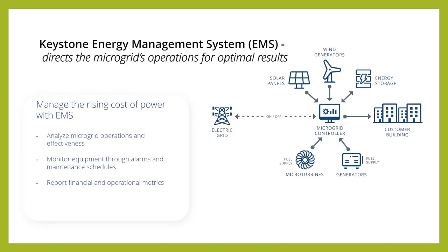People often ask, if you don't have these meter records, what can we do? And the answer is there's lots that we can do. We can use partial records. We can take records that are taken more infrequently. We can even go from past bills and build a model ourselves of what the building is probably doing in order to get this kind of data. So again, let's not let the perfect be the enemy of the good here. We'll use whatever data you have. Some data is better than no data, but even in the case of no data, it's important to have a conversation, because this is, again, the design phase. This is the start of the sales cycle and how you go about doing an energy storage project.